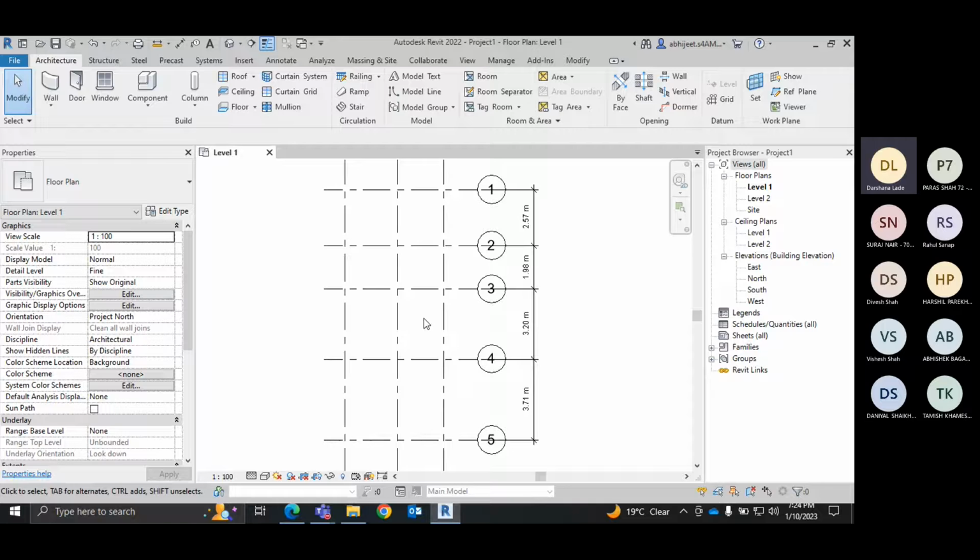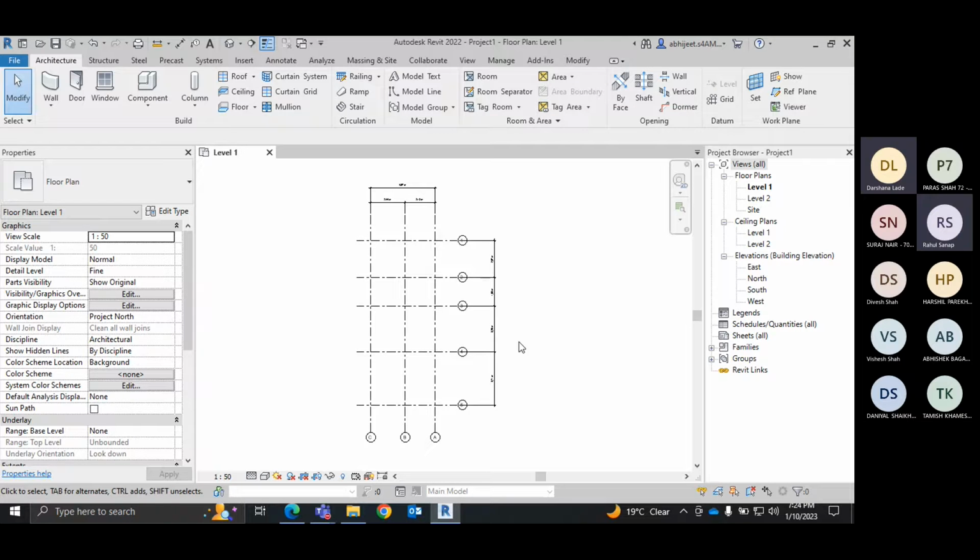The scale is 1:100. If we make it 50, then you can have everything in 1:50, right? Yes. Actually, no need to adjust the scale, because when we are creating the sheets, then you can define the scales according to the views. Sometimes for the floor plan it will be 1:100, but for section and elevations we can double the scale, like 1:50 or 1:20.